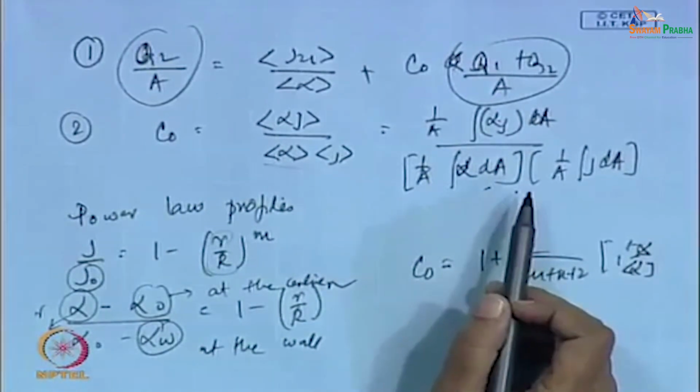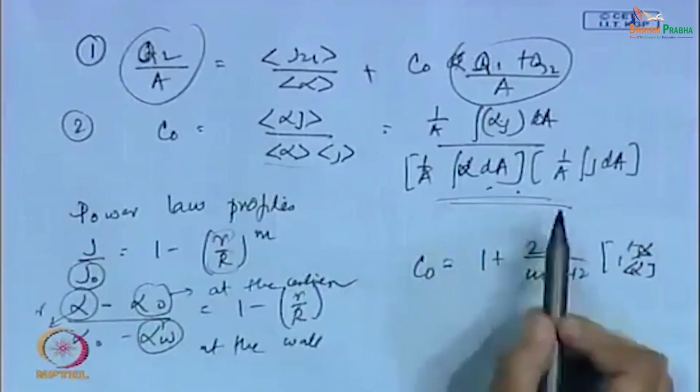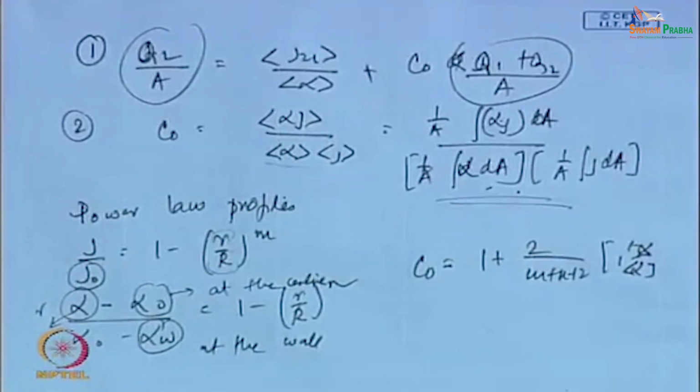There are two particular cases. One is when there is a heat flux and intense vaporization at the walls, so there is a larger vapor concentration at the walls as compared to the center. The other is when we introduce air through, say, a porous wall. Then in the developing region, there is a greater concentration of air bubbles at the wall as compared to the center. For such cases, we cannot use the C0 values which I have written down in my PPT. They are mostly for fully developed flow cases or for those cases which have a parabolic sort of profile. For anything else, C0 has to be derived from the basic equation which I have written down.